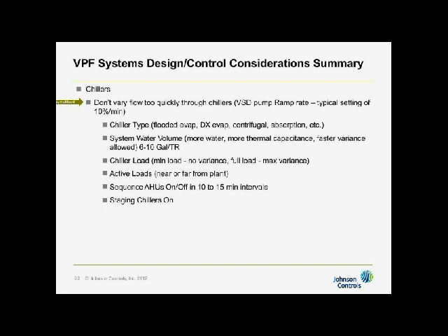Go to the panel on the pump and look for the ramp function on the variable speed drive. It's usually in seconds to go from 0 to max speed or max speed to 0. It'll be an accel rate and a decel rate. Acceleration rate, deceleration rate. It'll usually default to about 60 seconds, which is 100% per minute, far too fast for any chiller. So you just change that to 600 seconds, there's your 10% per minute.